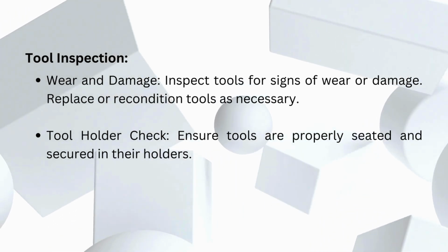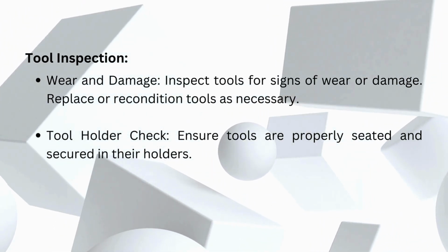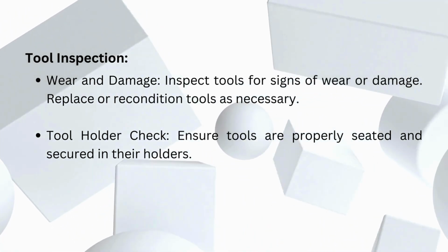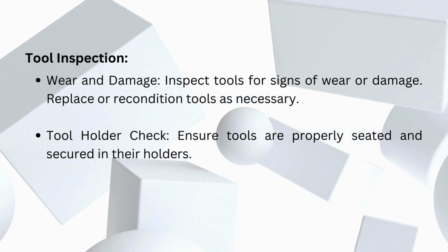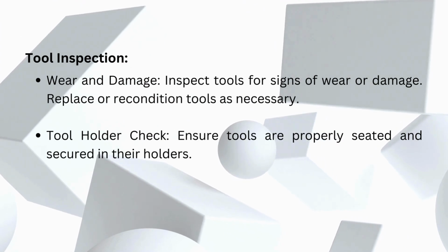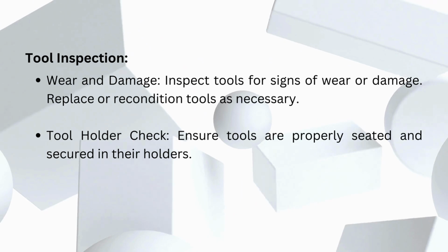Tool inspection. Wear and damage. Inspect tools for signs of wear or damage. Replace or recondition tools as necessary. Tool holder check. Ensure tools are properly seated and secured in their holders.